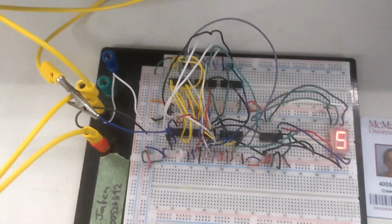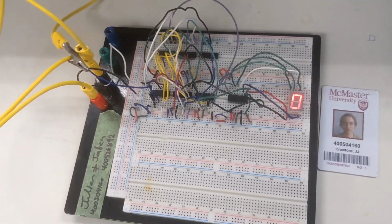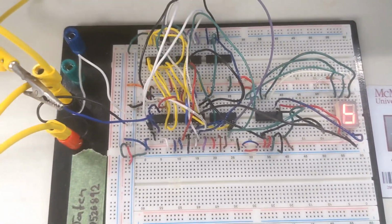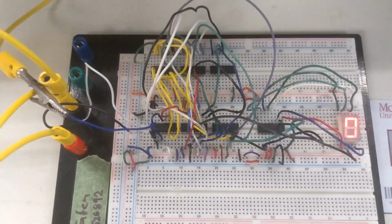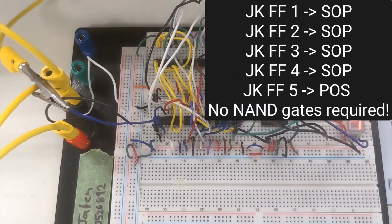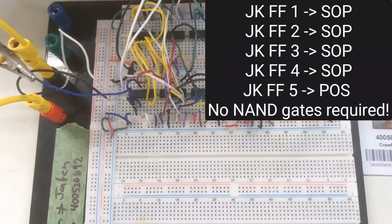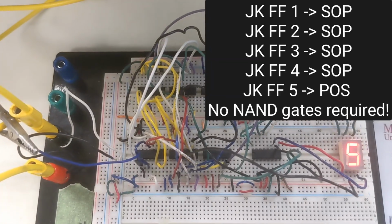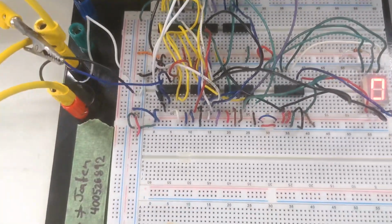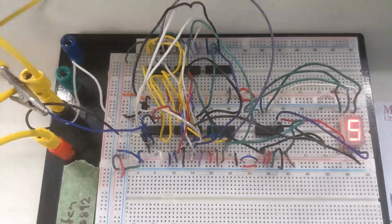Now, to optimize this and use as few ICs as possible, we had to choose whether we wanted to use a SOP or POS implementation. For most of these, we use an SOP implementation to get away with using a couple OR gates, but for some of the JK flip-flops, we had to use a POS implementation to get around using NAND gates or not AND gates. Whichever solution was the most efficient is what we used to reduce the amount of logic gates required.